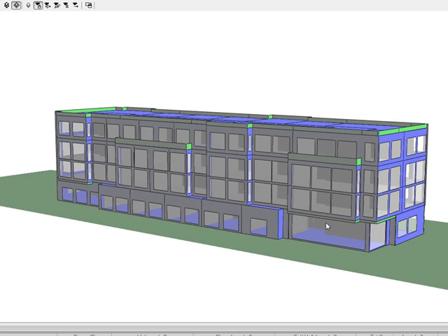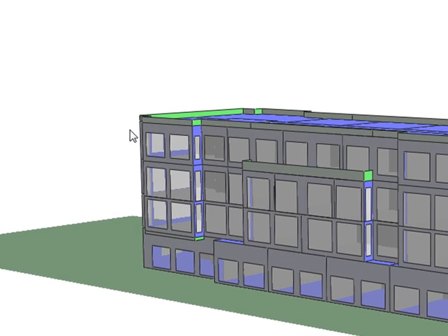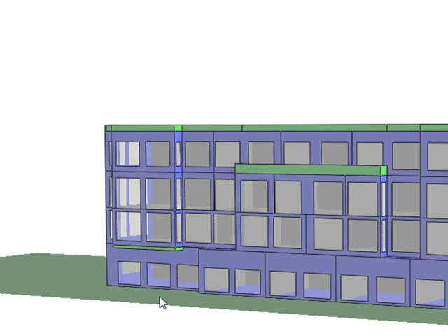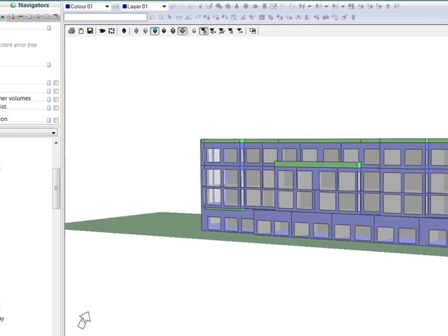Something that's very common is you'll see a telltale line of green between floors. You may have your base offset for your rooms not set high enough, and this is a very typical thing, or you may not have on your calculate room and volumes.